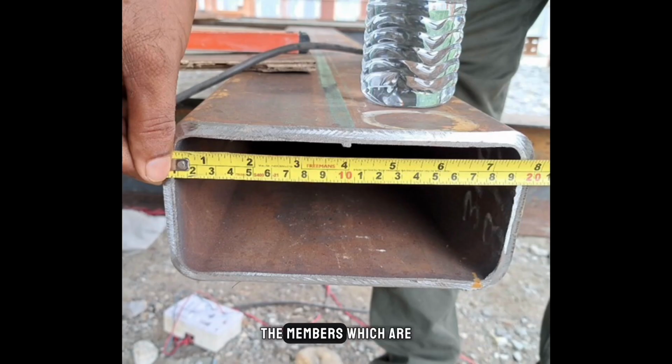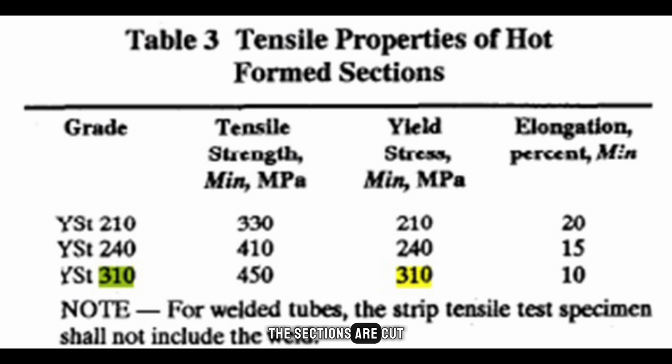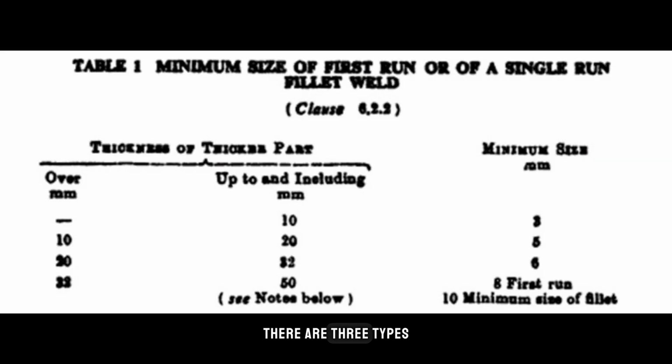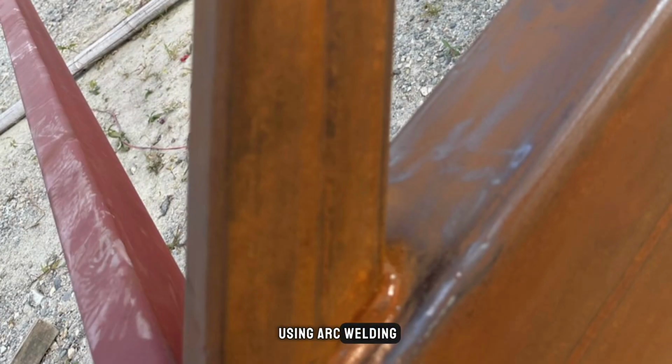The bridges over the open outfalls are steel bridges of rectangular hollow section of grade YST 310 according to IS 4923. The members, which are prepared in the factory, come with all the tests carried out, and in the field the sections are cut and measured with reference to the drawing and design and welded together. There are 3 types of welding: gas welding, arc welding, and electrode welding. In this project the members are welded using arc welding.